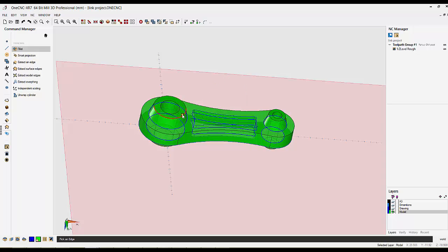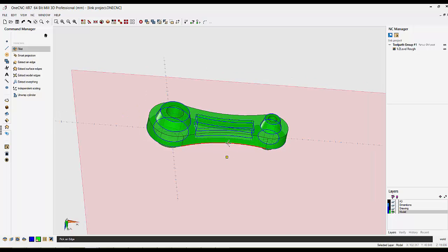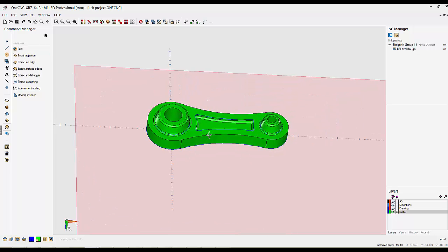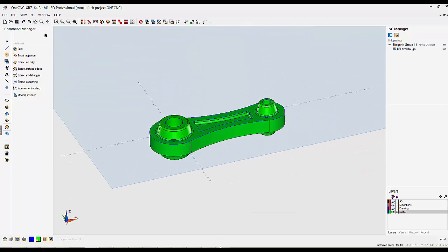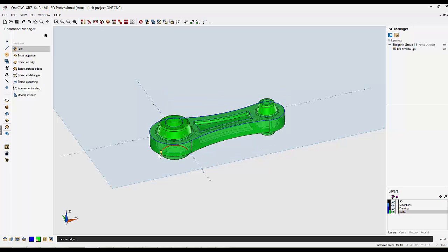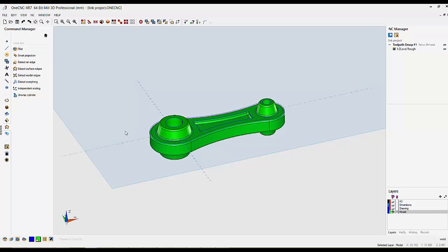profiles. There's radiuses on the top of these pyramids as well. So we'll grab hold of the top of these pyramids and right click. Okay, I did forget one thing. We have radiuses going around the main profile as well. So back into fillet, select the outside profile, top and bottom, and right click.